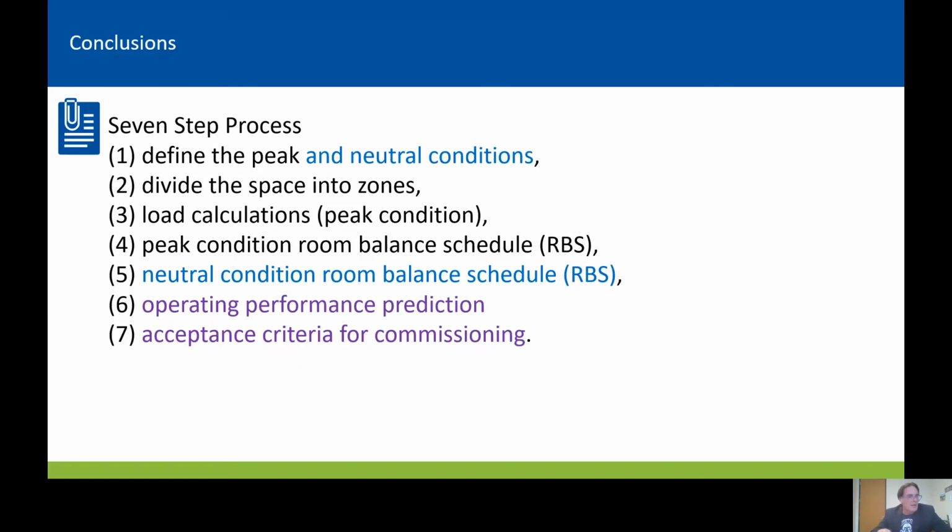I don't know if my reputation precedes me with the audience or not, so I'll go ahead and say it. I do have a history of being critical of code ventilation rates. I believe a lot of them are arbitrary and historical carryovers, which are wasteful and don't actually provide value. But that's really not important right now. The biggest gap that we see in energy and performance is in the design engineering community. Design engineers are not designing systems to reduce air down to those code minimums.